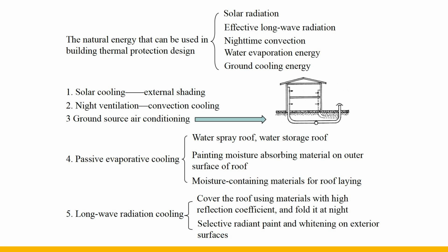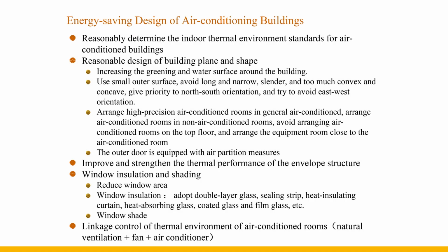Long-wave radiation cooling is the use of nighttime radiation to cool down. It is suitable for areas with a large temperature difference between day and night. To achieve a better cooling effect, the building skin can be treated with light color and painted with selective radiation paint. The energy-saving design of air-conditioned buildings should pay attention to the following aspects.